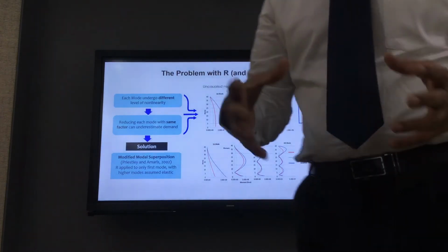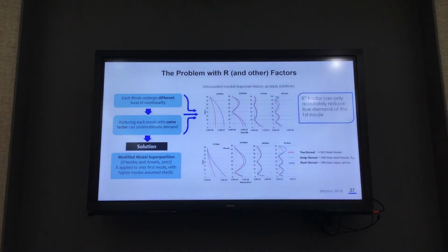When you put a lot of vertical reinforcement in a shear wall, the moment capacity will increase. Is it difficult to imagine that when you put vertical reinforcement in a shear wall, the moment capacity of the wall will increase, right? So you are a little bit correct that the yield strength or yield capacity will increase. You're also correct that the failure might shift to shear, but I want the right answer. Step number 1, moment capacity will increase.